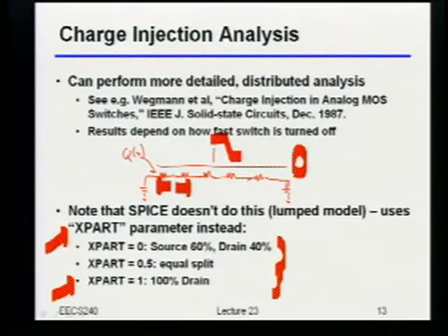By the way, when I talk about source and drain here, I just mean which terminals you instantiated as source and drain in your SPICE deck. Right, so whichever one you called first would be one, then the other for the second one. Or sorry, I just mean that when you say M1, drain, gate, source, body, it always treats that first terminal as the drain, and always this terminal as the source. Okay? Yeah?